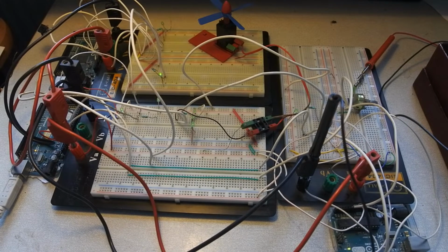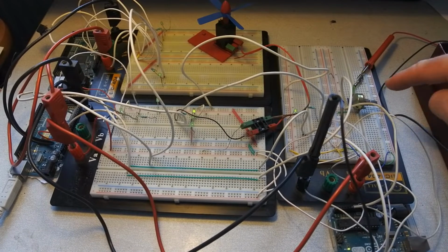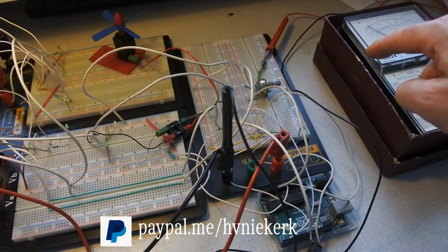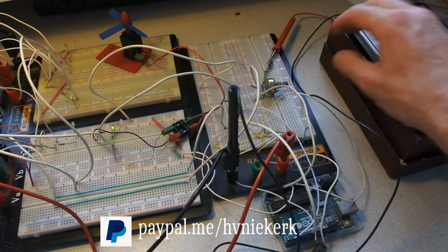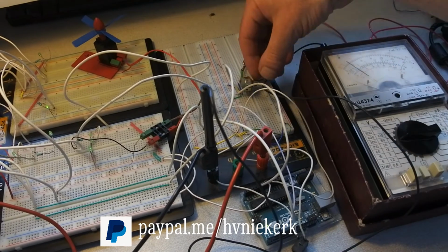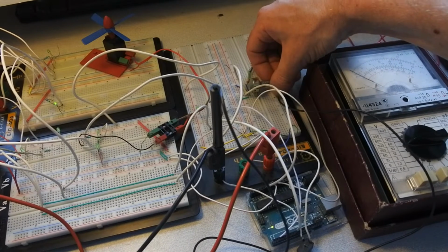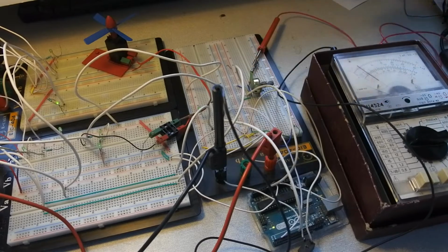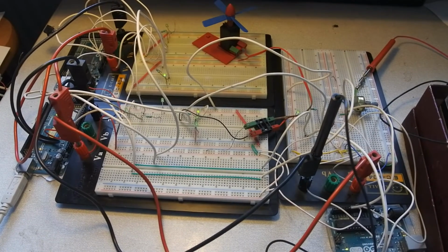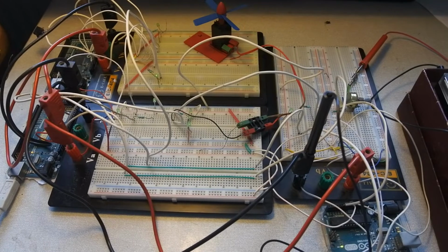So where does it lead me? Well, end of the data acquisition. What next? Well, I can still try to get voltages being read, and I can check those voltages here with this multimeter, potmeter, and if you can see this needle, I turn it, this is maximum, and slowly to 0, then back again, and it gets to 4 something, never 5. Is that correct? Well, there's 5 volts and there's 3.3 volts, so it's something in the middle.